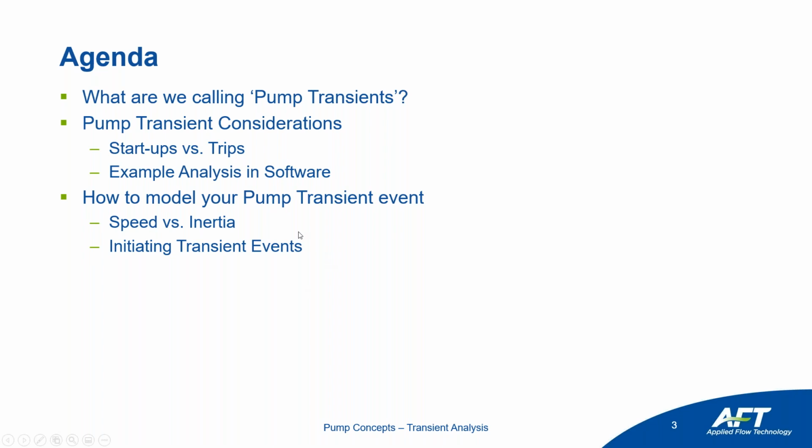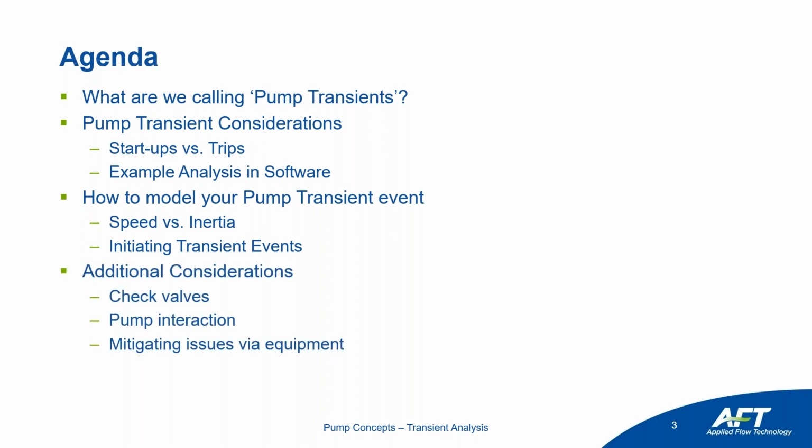So what's going to trigger your pump startup, or what'll trigger your trip, and then also how you can become much more complex with multiple criteria, or trip your pump, then restart it after a certain amount of time or after a criteria is met. As kind of a final aside is some other considerations when you're doing transient analysis on pumps.